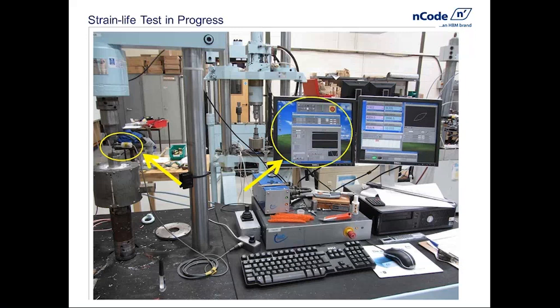That is the control panel. In the modern medium, we have a GUI, and that GUI has the knobs and buttons that would have existed on an old analog machine. We can press those buttons and sort out the loads and so on. And that is the diagnostic display. It confirms the settings that you've got. It shows you what hysteresis loops, stress versus strain plots are coming out of the machine, and tells you very rapidly if anything's going wrong. And that, as I say, is a typical test in our lab.